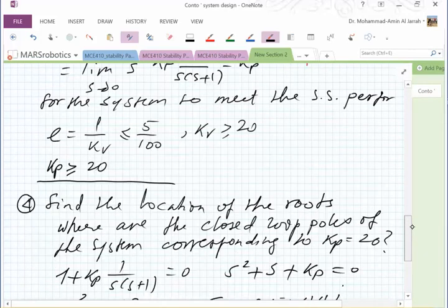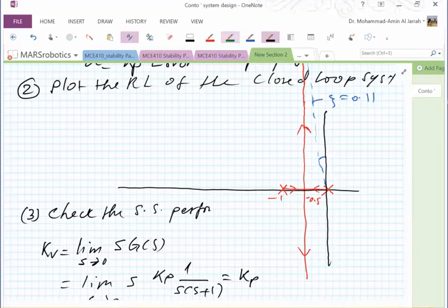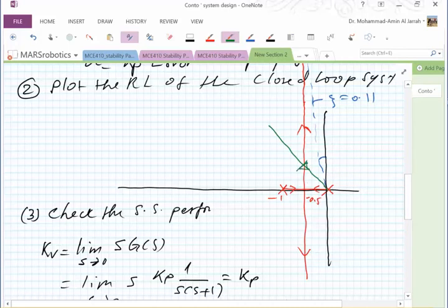If we go to the root locus here, the 45 degrees, I will sketch it here in green. This is the 45 degrees. This is zeta equal 0.707. What is the customer happy with? The settling time. What is the settling time in this case? 4 over 0.5. It's 8 seconds, so it's maybe too long, but the customer is not worried about it. He's worried about the overshoot. He does not want this overshoot.